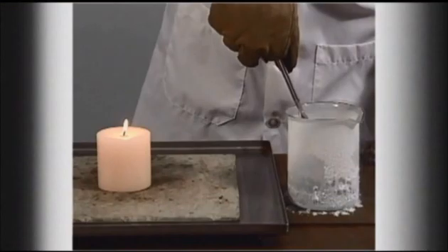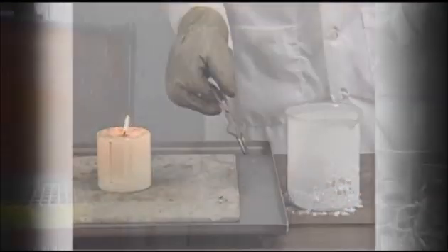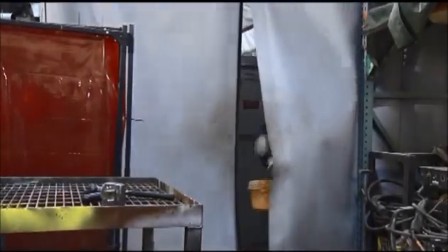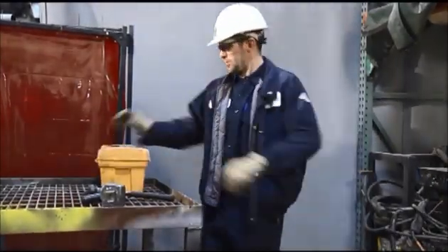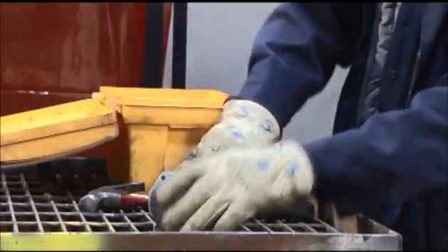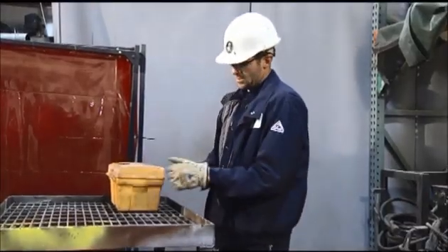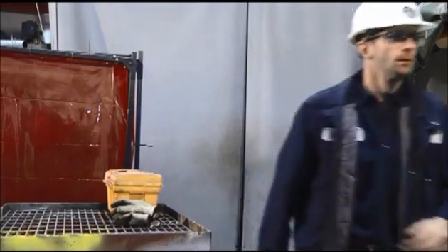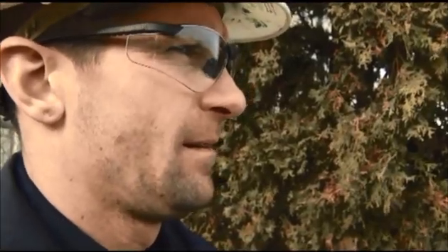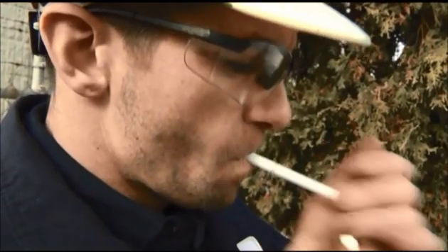Even a steel wool pad will burst into flame after being immersed in liquefied oxygen. Clothing and other materials saturated with oxygen are especially susceptible to fire. In one documented case, a maintenance worker performed a job inside a closed vessel with high levels of oxygen, which saturated his clothing. After the job was done, he left the vessel and decided to have a cigarette. He struck a match, the ignition source, and it ignited his oxygen-saturated clothing.